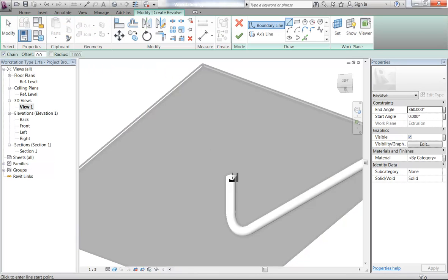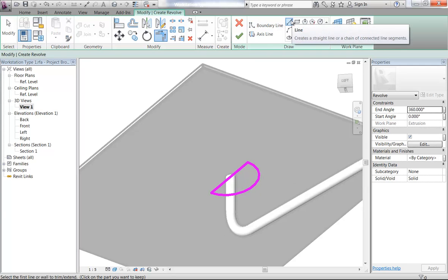So I'm going to go just by eye from the center of that stand, or arm I should say, and just do a straight line. And then I'm going to come out and change it to drawing an arc, and then bring that back so it's centered. That's about right. Trim. Okay, so it's a semicircle, in other words, just for a revolve, and then my axis line will just be a straight line following that center.